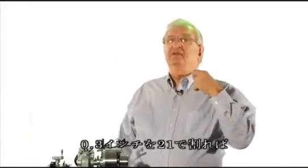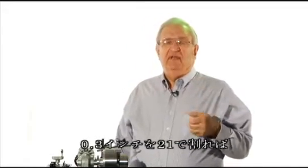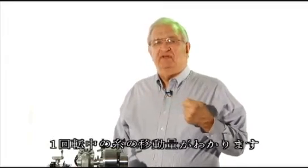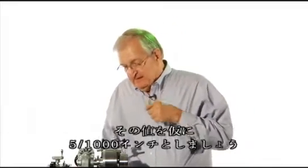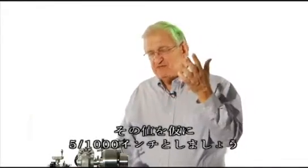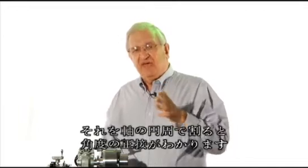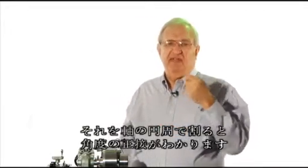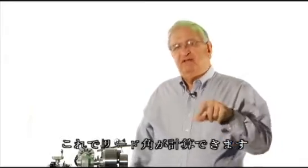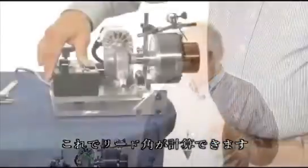So that means that you take 300 thousandths, divide that by 21, and you get the amount of travel that string went in one rotation. Then you take that amount, say 5 thousandths, and divide it by the circumference of the shaft, and that gives you the tangent of the angle. Then you can calculate the angle whose tangent is that number.